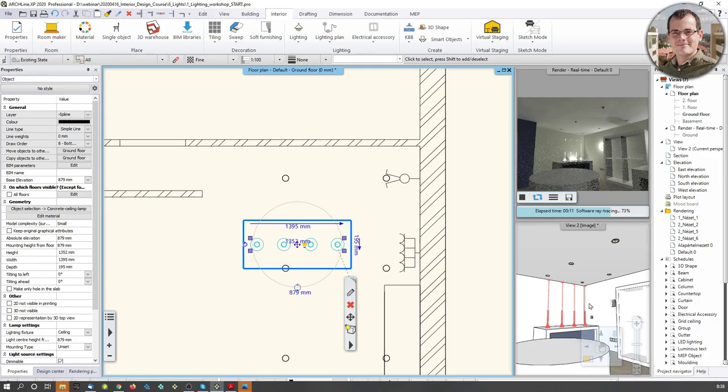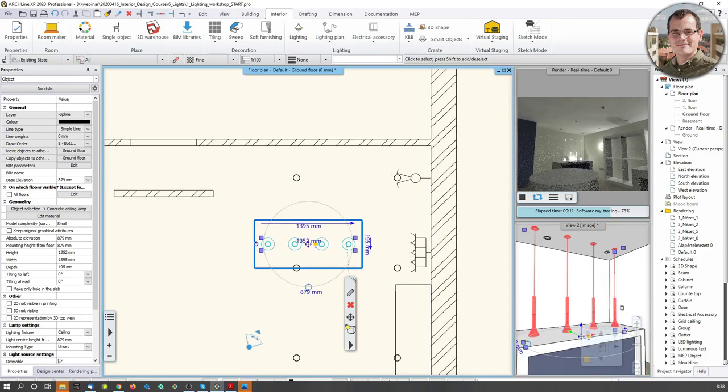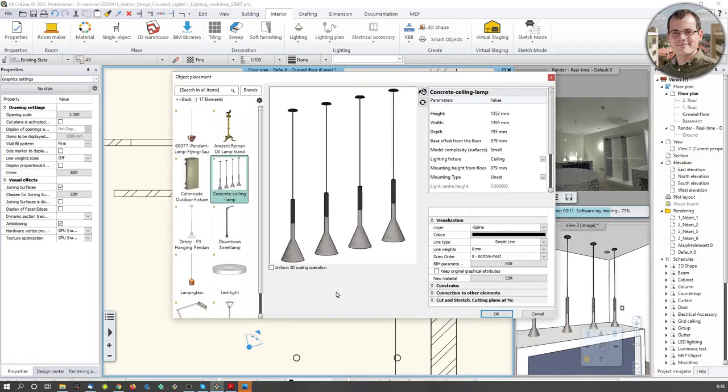Lamps are too large, so I'm going to have to go to the properties and define the sizes, which I think I can do with the pencil icon, and then I can just change the sizes. So let's do that first before I change anything. Click the uniform 3D scaling, because then if I change one value, all the other values are going to be scaled as well, so I don't have to worry about stretching my items. Another thing I have to check is the material settings.